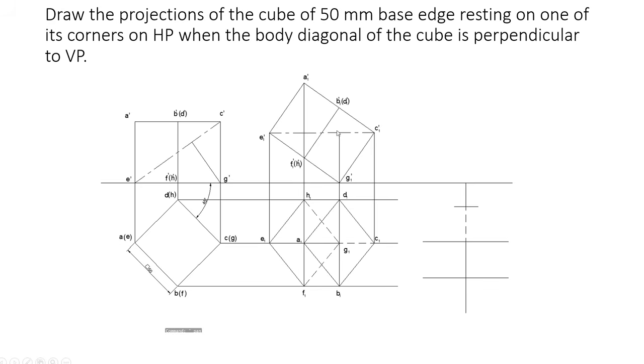So now this is parallel. If you rotate this diagram through 90 degrees, this will become perpendicular. So copy this diagram in such a way that you rotate it through 90 degrees. For that, just draw a vertical line like this, mark a point here, and from that point you mark this distance and this distance. That will be same. Okay, same distance, this distance here to here, here to here, that is c1 g1, g1 a1 and a1 e1.